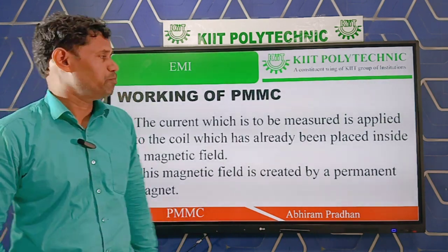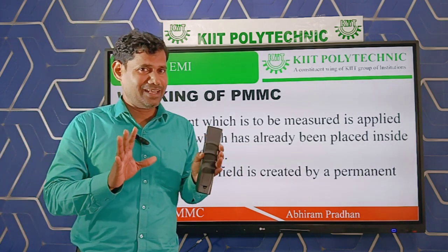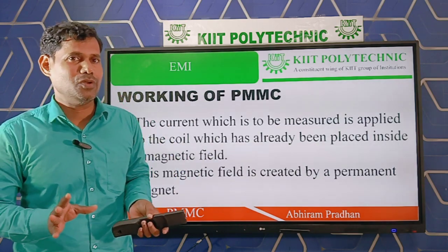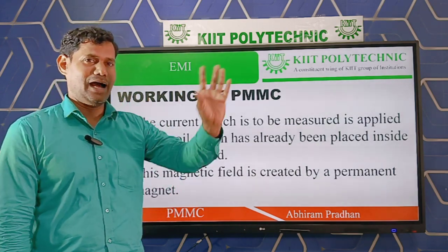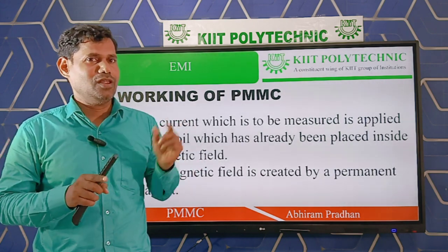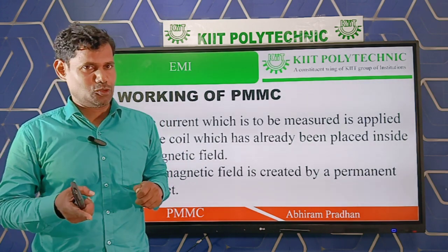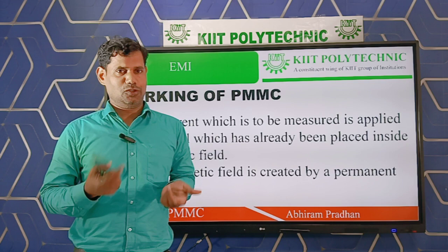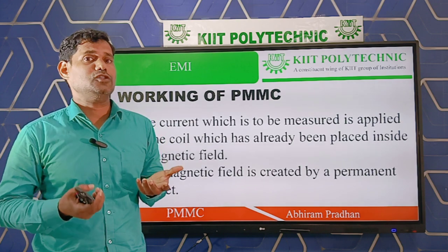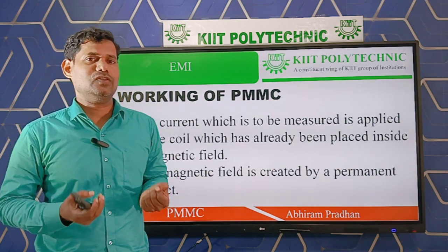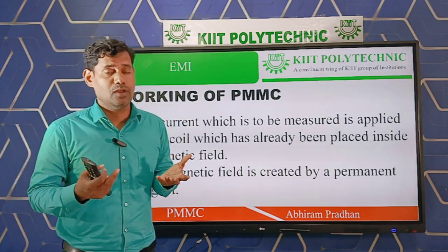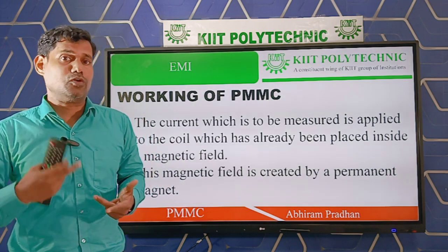Now, the working of a PMMC. I have shown in the diagram how it works, and I am stating it again. When current passes through the coil, it experiences a mechanical force, and that is the principle of a motor. That's why we always say PMMC works on the motor principle.